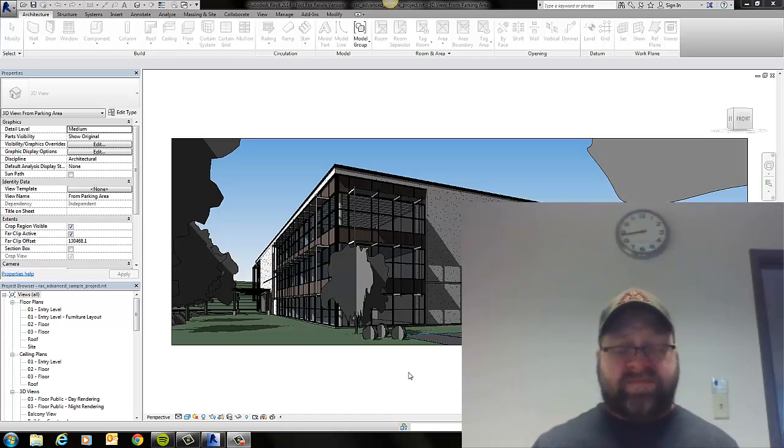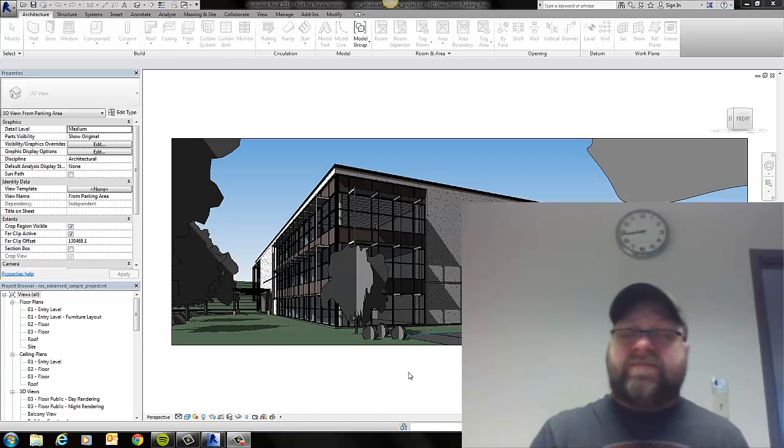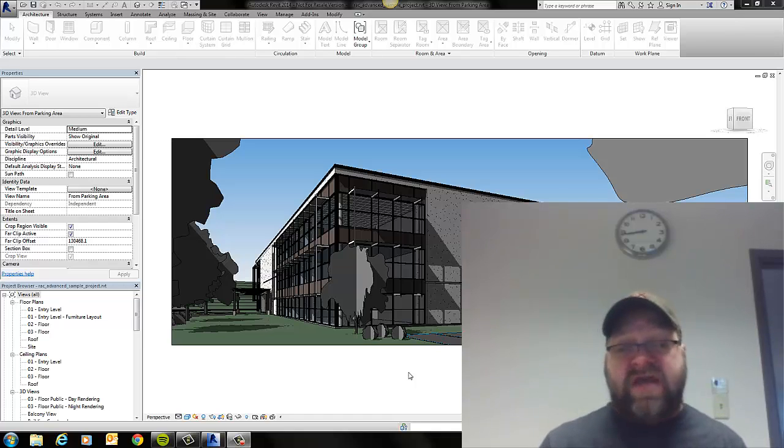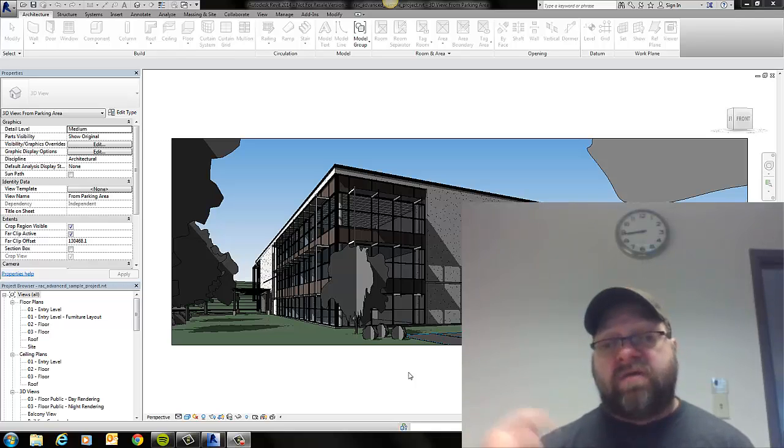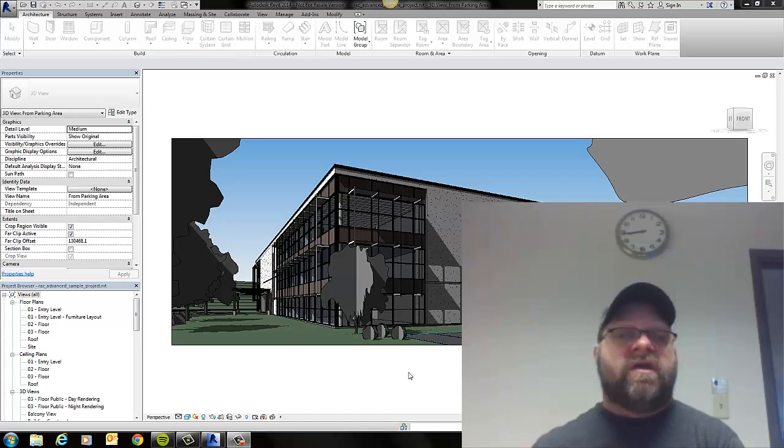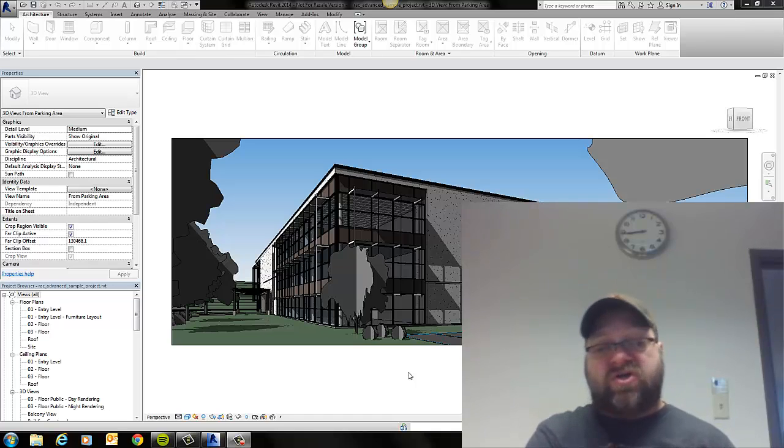And the categories are typically by function. So Revit provides a much more consistent experience because as a user, you can't really control what the categories are. They are predetermined. So you get rid of all of that kind of labor of needing to, when you're authoring an object like in CAD, make sure you're on the wall layer, make sure that's all set correctly, and then draw your object. In Revit, you just pick the wall tool, it automatically goes to the wall category, and you don't have to worry about whether it made it to the right spot or not, or having somebody put a bunch of exterior walls on an interior wall layer. That's just not going to happen.